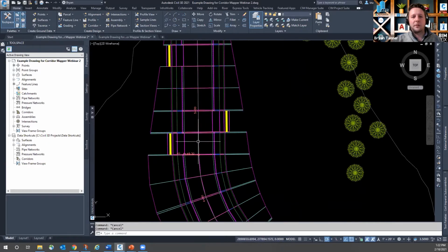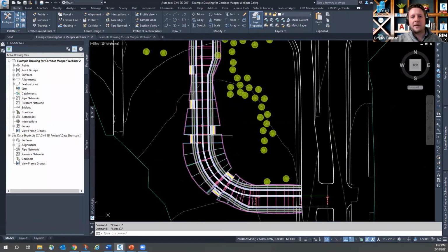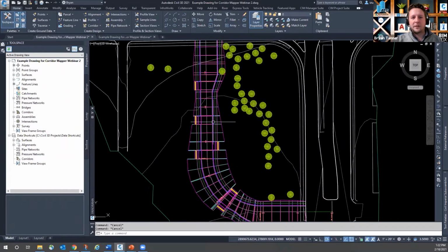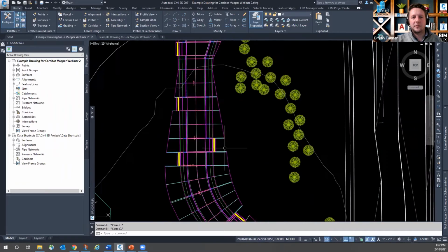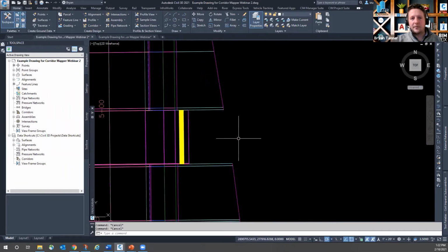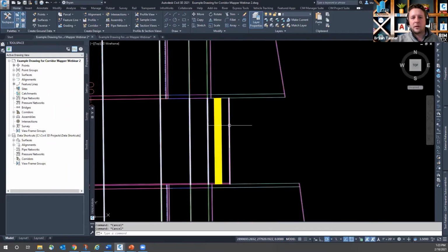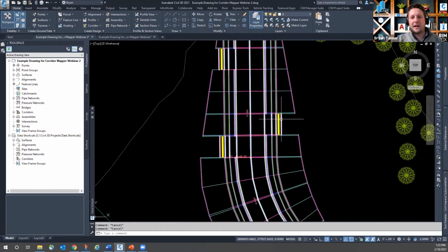And if we're cutting 50-foot cross sections and maybe supplementary drive cross sections, then we just need to make sure that we have an accurate model that's going to be represented in our quantities and in our cross sections on a project under those circumstances. So we're going to stick with this for the time being, and we're going to talk a little bit more about our targeting options. Certainly, I could set a feature line out in space and define that as my right-of-way or my target line for my horizontal and vertical location for my back drives.